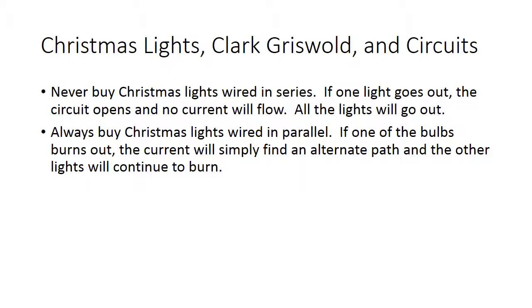If you buy Christmas lights that are wired in parallel, when an individual bulb burns out, there are other paths for current to flow, so those other lights will continue to shine, and you can go immediately to the bulb that's burned out and replace it. So don't be a Clark Griswold. Buy your Christmas lights wired in parallel.